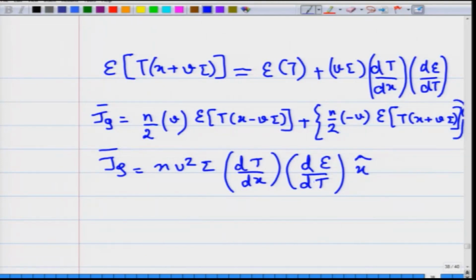This is the heat current in this one dimensional piece of a metal where you have maintained a gradient in temperature across the metal, and how much is the heat current which is flowing across a given point x, and that you have a very general expression for this. And this, if you recall, Jq will be, I am sorry, there is a negative sign here, there will be a negative sign which you will get out here, and this is nothing else but in one dimension the thermal conductivity into dT by dx, okay.